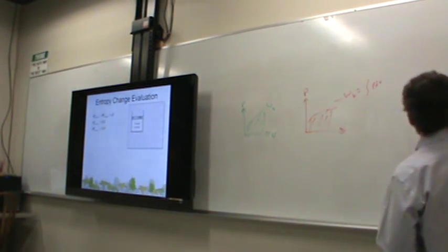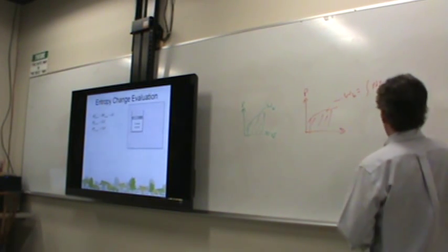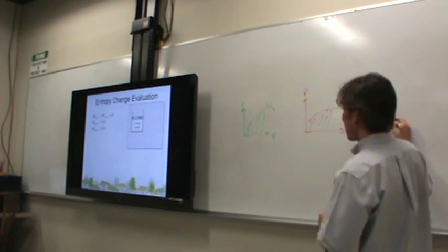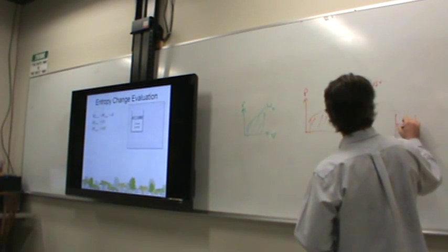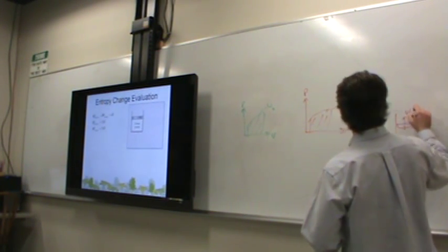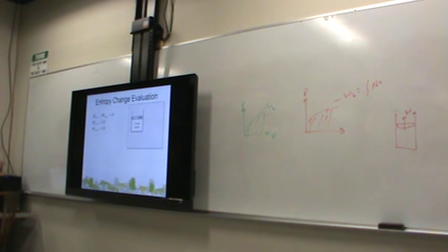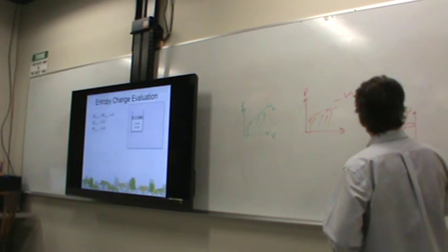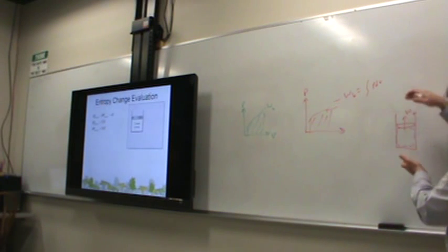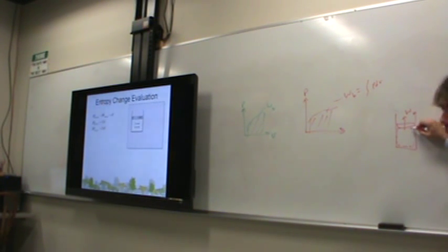Think about it. This is actually pretty easy to show. You've done a lot of piston cylinder problems, right? Or at least you've worked on a lot of piston cylinder problems. Okay? What have we always said about the piston that allows us to calculate the boundary work that actually comes out of the system? It's just floating there. It's internally reversible. There's no friction. We also made the requirement that the gases do not expand quickly, because if they expand quickly, the pressure against that piston is going to drop, right? And you're not going to get as much work out as you expect.